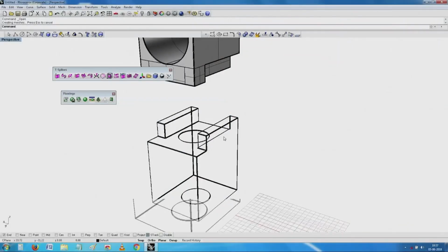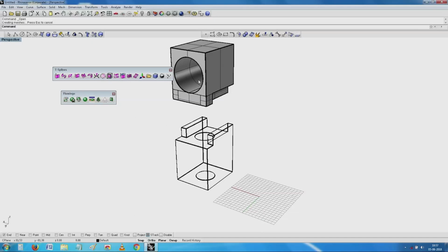So while it is correct at this point, what will happen in case there is one more opening which comes in the other direction? I have one here, two I have managed. Now, imagine I have one more which is coming in this direction, what to do now? If the job permits, it is always possible for us to break it up into small parts, alternatively put up with it. You have no choice, just put up with it. When you put up with it, you lose a little bit of both the support material and build material, but in principle it is possible to do it.